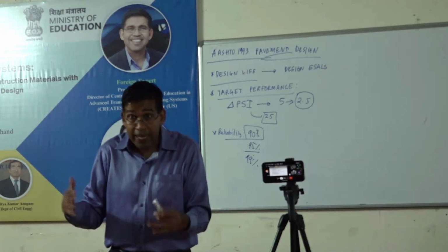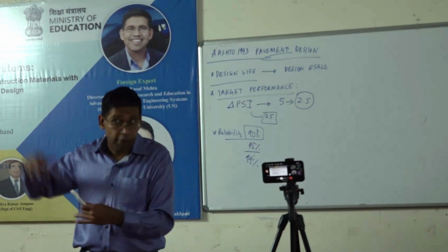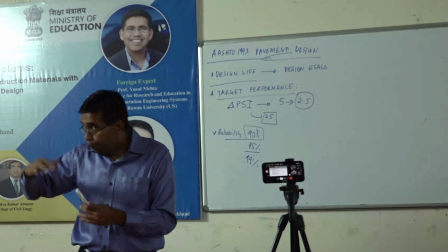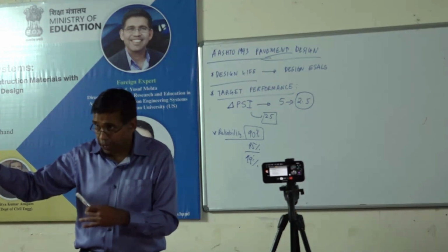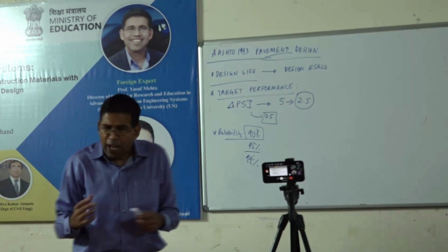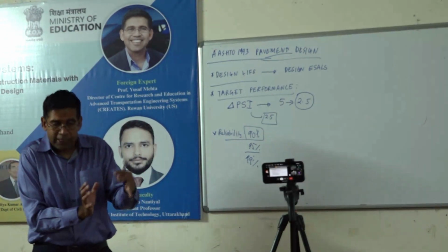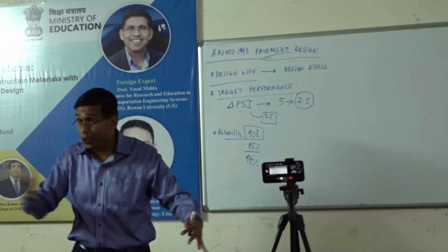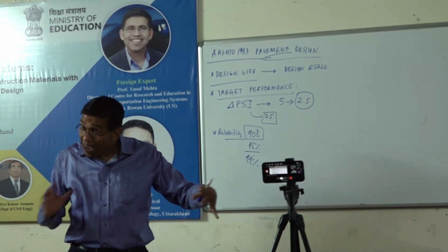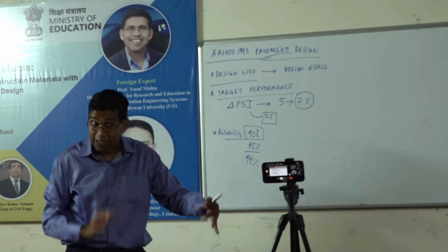Cost, yeah, you will make the design conservative, right? You will start to put that subgrade away from the load. You will start to put stronger, thicker and thicker and thicker materials, right? You see what I'm saying? So that's the tendency. So I'm going to give you the theme here, right? The AASHTO was done in the 1950s and 60s, right? Now we are in 2025. So everywhere there is an inherent factor of safety being added in all these places.